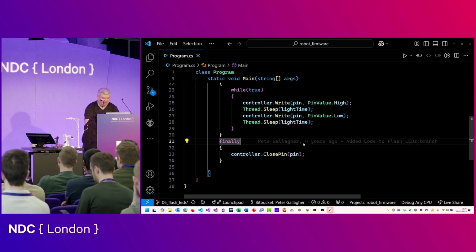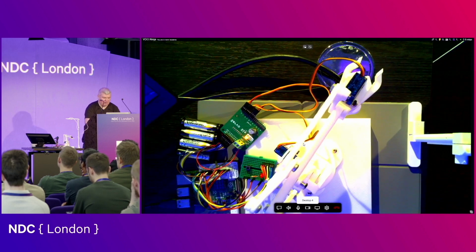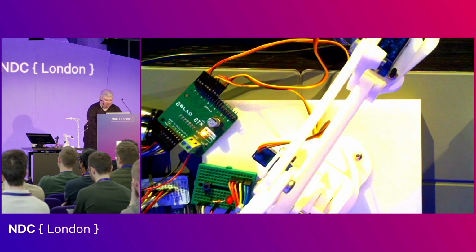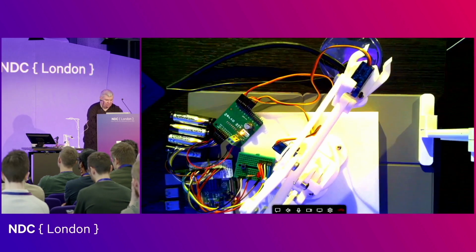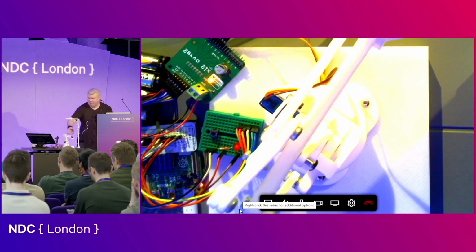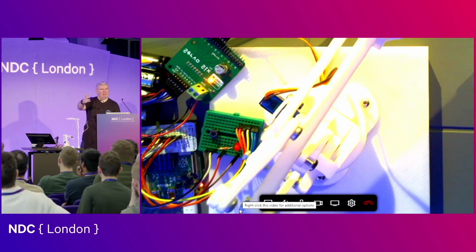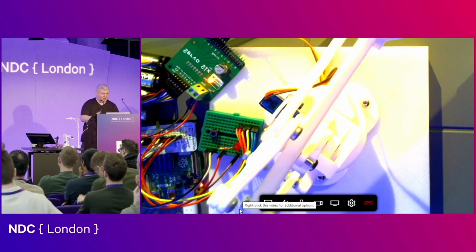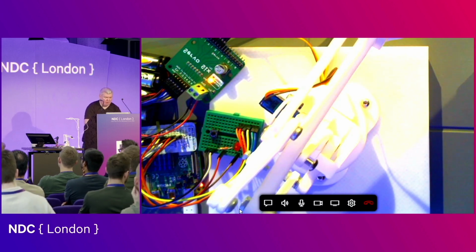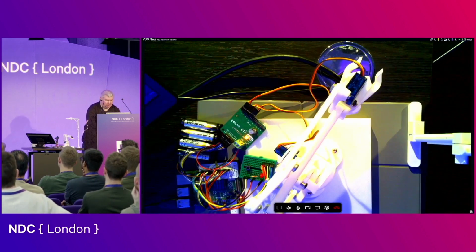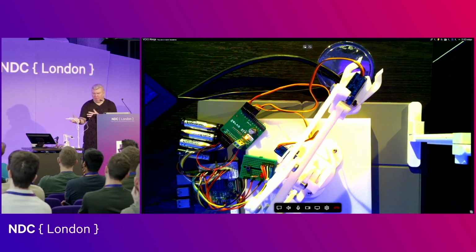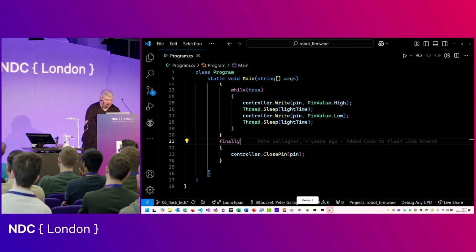And when we run it, then we get a flashing LED, which if I use that one instead, we can see our flashing LED. It's not all that bright, but you hopefully see that flashing away. So that's good news once you've got to that point, because now we've got some level of control, but we really need an input as well, so we need to read a button. So we stop that code.